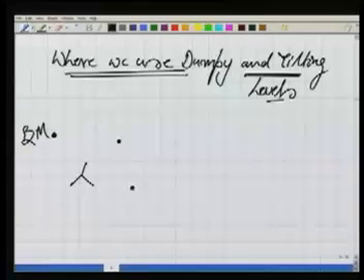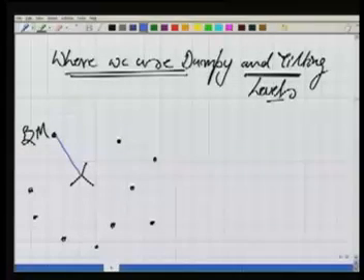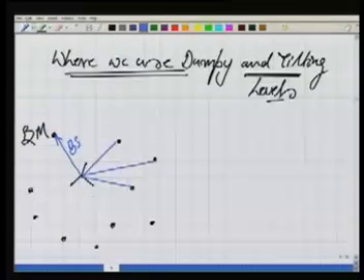There are many more points for which I need to determine the RL. I know the RL of the benchmark. So the procedure is, once I have leveled my dumpy level, after taking this back sight, I can take several foresights to each of these points.